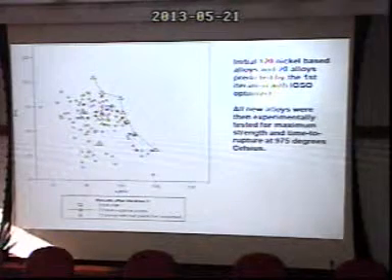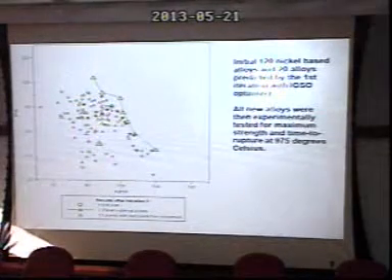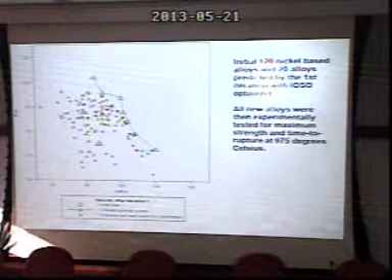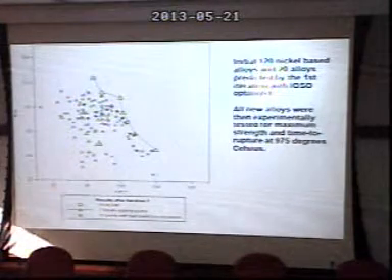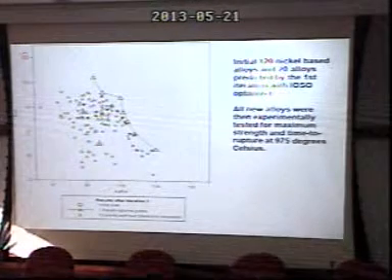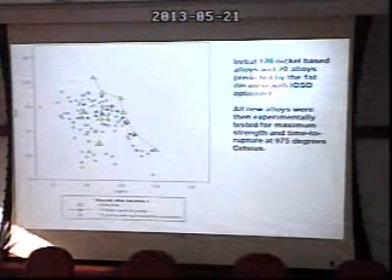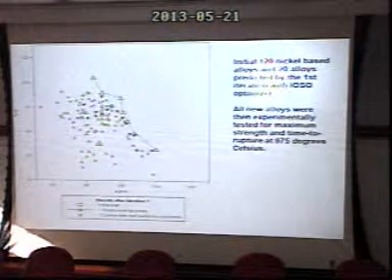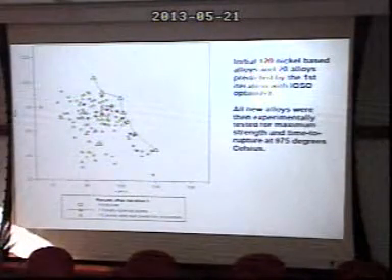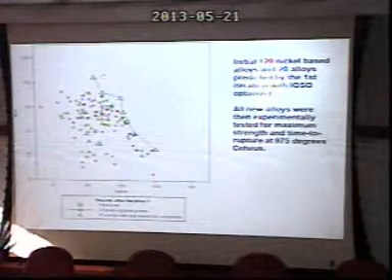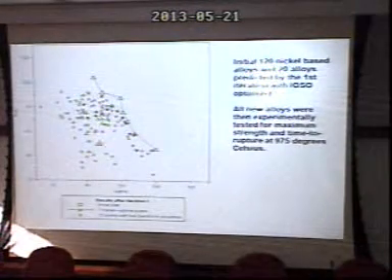This is an example of the power of algorithms that we engineers have already created and used in other fields to design new alloys. This is an example where 120 steel alloys have been created and manufactured. Their tensile stress is plotted here, and the time until rupture is plotted here, measured at 975 degrees centigrade. Feeding this 120 alloy information, experimentally obtained, into the optimization software, the software created 20 new suggestions for 20 new alloys that should be better than any of the 120. Well, after they were manufactured and tested, it looks like some of them are the same quality, but a bunch of them were truly better. Okay? Higher tensile stress and higher time until rupture.